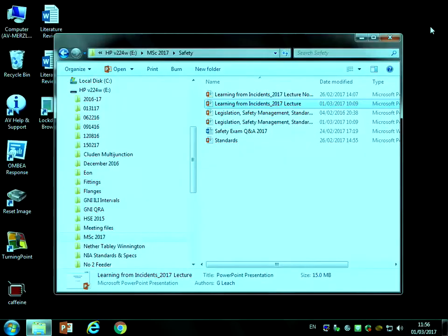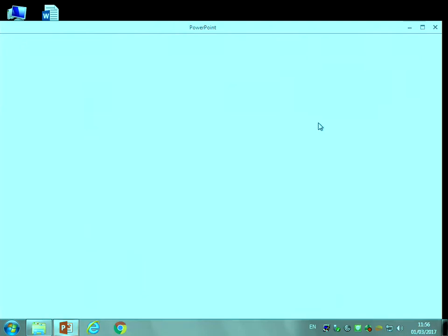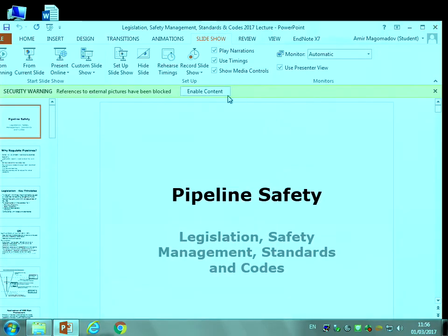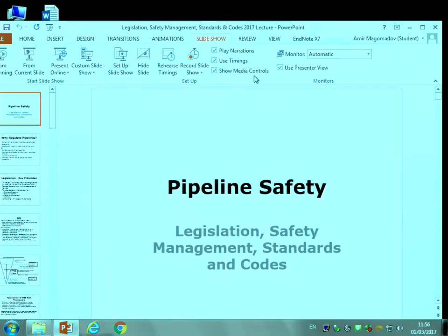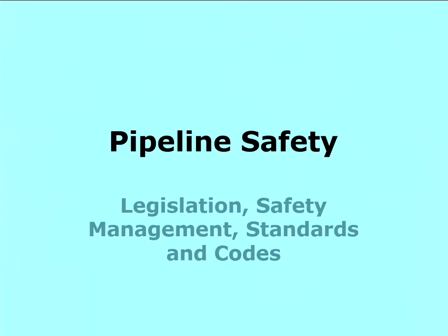Leaving controls totally to operators and stakeholders is not really a good thing to do. So you've got to legislate. The legislation has got to require safety management, and then you must pick up the details that have got to be actually applied in the pipeline design, construction or operation. You've got to get those details into standards. If you don't, they'll be missed and they won't be applied.